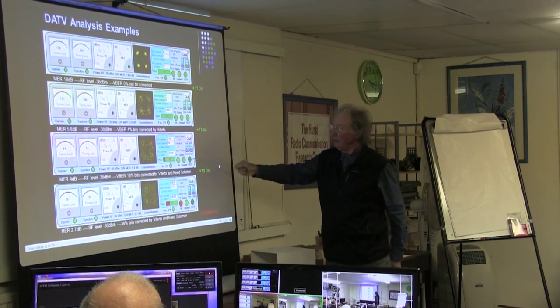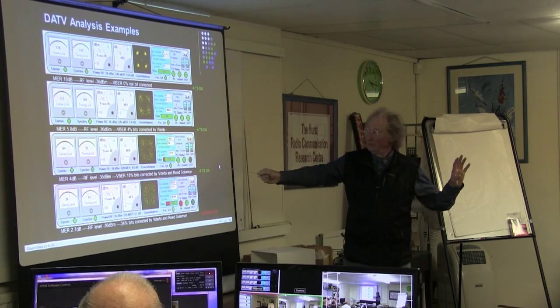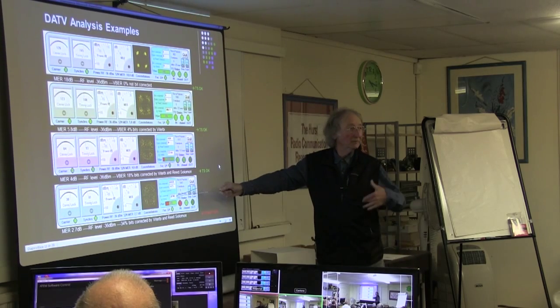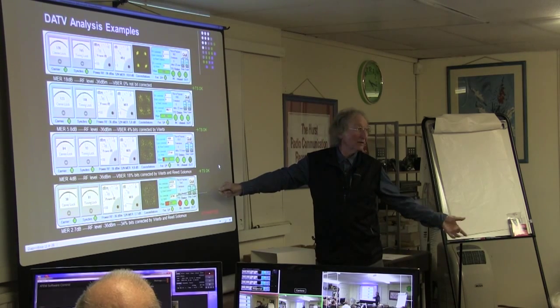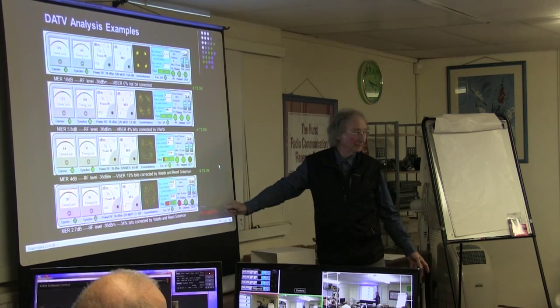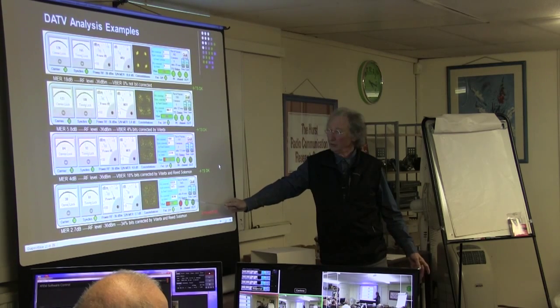And all is green. Okay, I continue to receive. But now the Viterbi corrector and Reed-Solomon cannot correct all the errors, and the transport stream is red. So I cannot receive now.